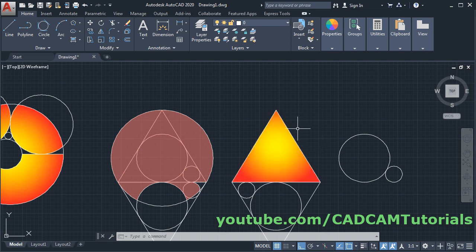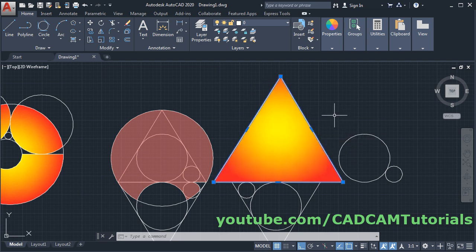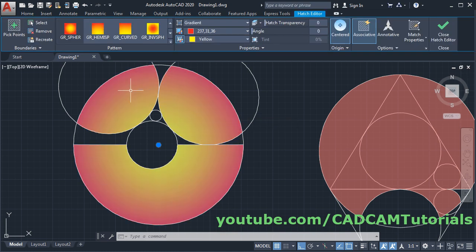If I click on this triangle, click on this grip and take it above, as per that, your hatch is updated. So that is associative. Press escape. Now here I have created this hatch using a single hatch command. Therefore this complete hatch is connected and single.